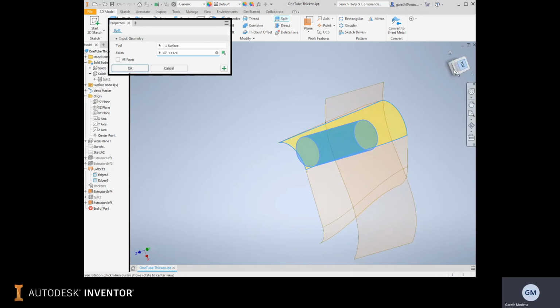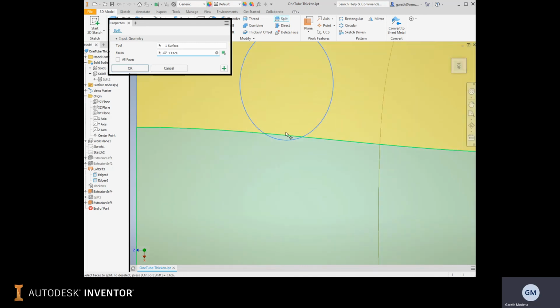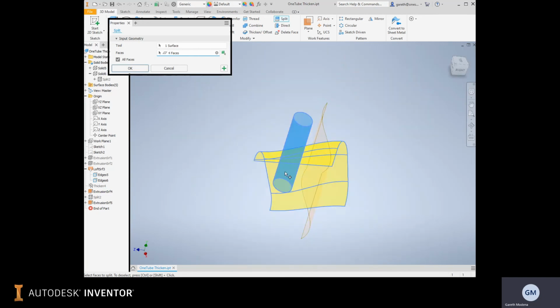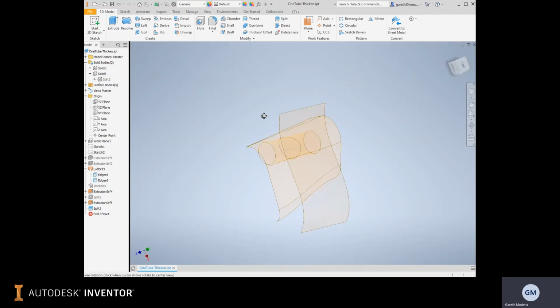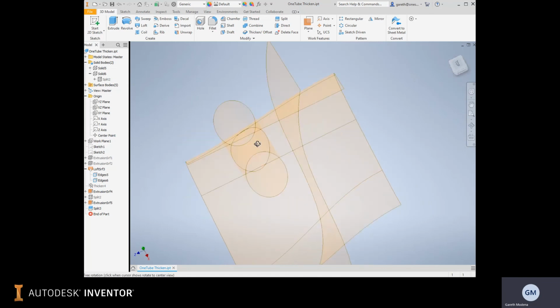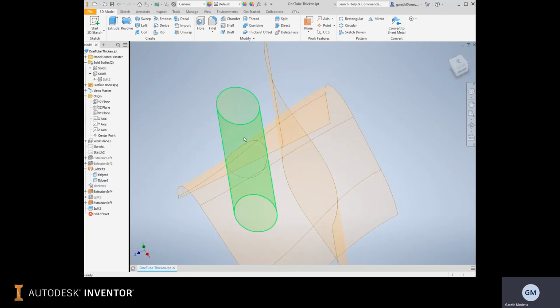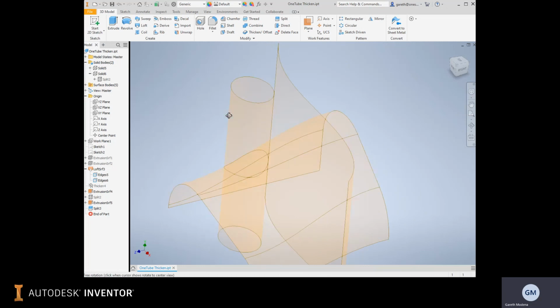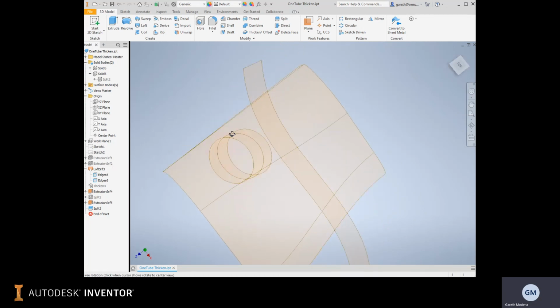This one's easy because it's actually totally enclosed except for that crossover there. So you will have some discrepancies if you don't select this one. Alternatively, you can select all faces. It'll actually go and try and cut across all of them. Obviously, it doesn't cut those anyway. And it'll generate a split profile of where this intersects with that. It doesn't have to be a linear extrude. It could have been a non-linear item as well. So that would have been another example that you could have used.